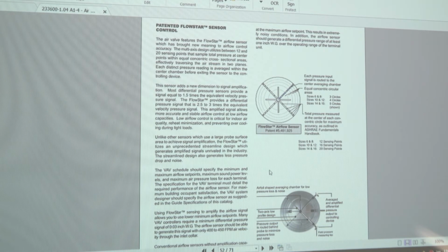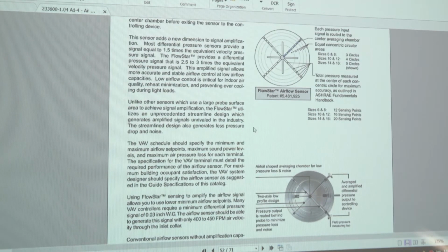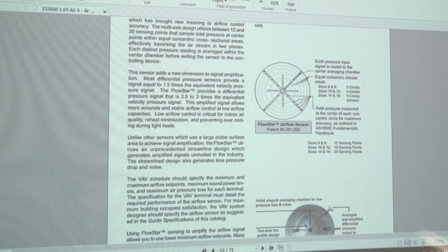They're all low voltage, 24 volts. There's common power supply panels located on multiple floors throughout the building that provides the 24 volt to power these control systems.